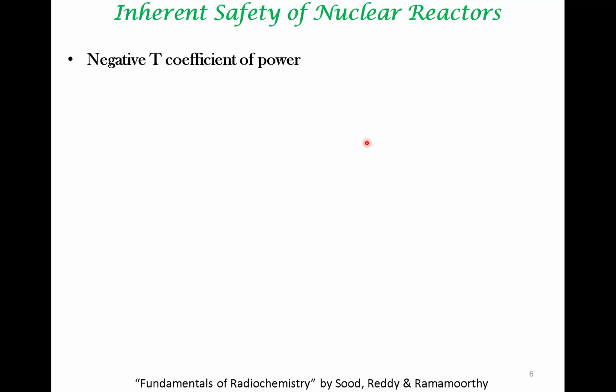One of the features that is troublesome in many other reactors, let's say if you look at the Bhopal chemical reactor failure, one of the main issues was the snowball effect. What is the snowball effect? As the temperature increases, the rate of reaction increases, and if this heat is not taken out, that goes to increasing the temperature once more, which increases the rate of the reaction.